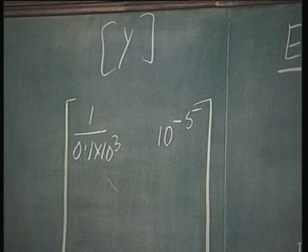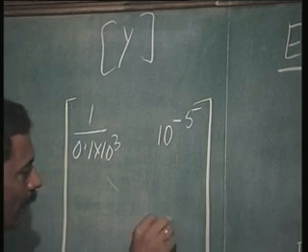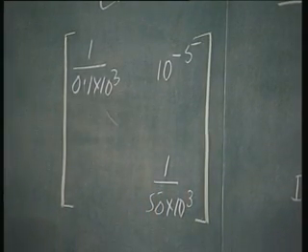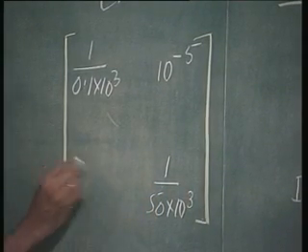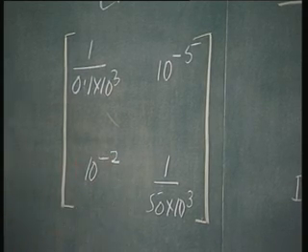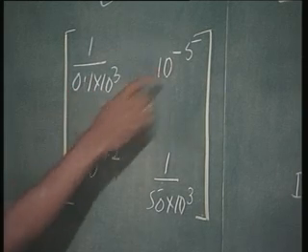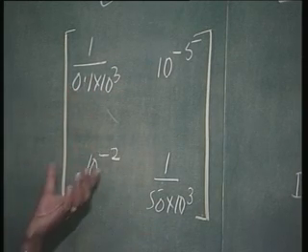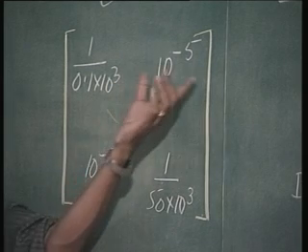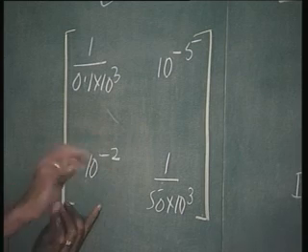Right? So now on this side Y naught is going to be 1 over 50 kilo ohms and YF is the main transmission 10 to power minus 2 Siemens. So all these are Siemens and you can see that this should be really a large factor compared to this in any case, so that it is more unilateral.